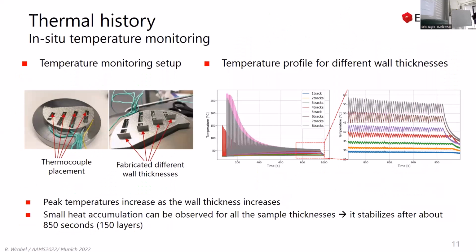So in order to track the thermal history, what is happening in the sample, we simply did a test using a thermocouple. So we printed a base plate with some channels where we attached the thermocouple, and we printed different thin walls on top of it.